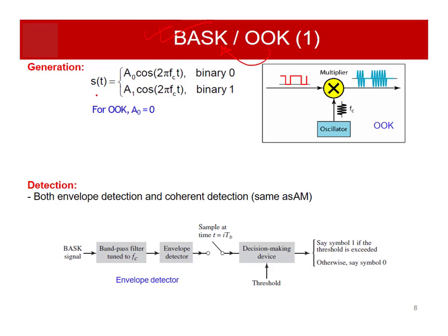So, let's say we have a digital bit sequence. First things first, we have to convert this digital bit sequence into a physically realizable signal through line coding. Here you can see the red signal is a line coded signal. It is something like 1 0 1 1 0 1, whatever. So we need to digitally modulate it by the amplitude shift keying modulation scheme. Of course, our amplitude shift keying is binary type, so we will encode each bit at a time.